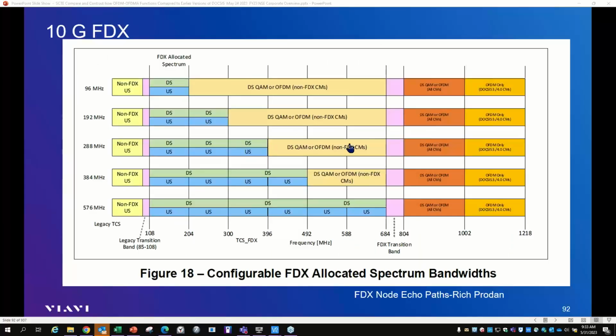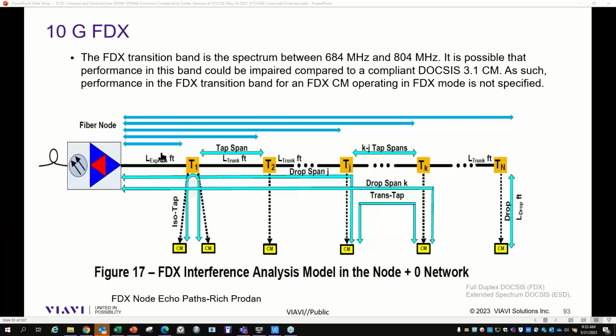type of technology, right? So based on the last expo, and even from previous, your number of active amplifiers is only at this point, I believe, only 3 active devices that can support full duplex. That means that if you have an optical node with a line extender or multiple line extenders, for example, they have to be able to switch on the fly in order to deal with upstream and downstream capabilities. Some of you might have gone to Expo and seen some of those scenarios played out there in demonstrations. It's pretty amazing to see that happening.